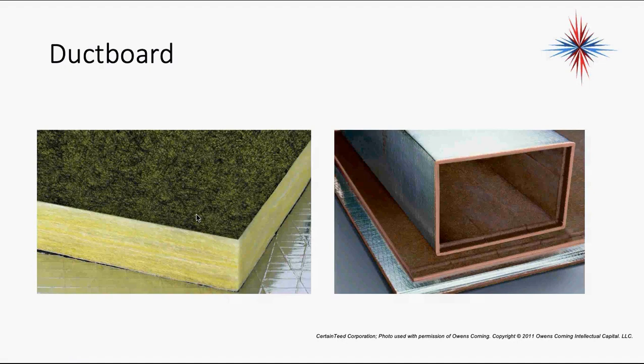So two guys working out of the back of a pickup truck can duct an entire house probably in a day. These guys are fast with the stuff. But it doesn't stand up to weather. It doesn't stand up to use. And then somebody will decide to have their ductwork cleaned. The brushes they use to clean ductwork will rip this inside layer apart. So now you have clean ductwork spraying fiberglass all over the place.